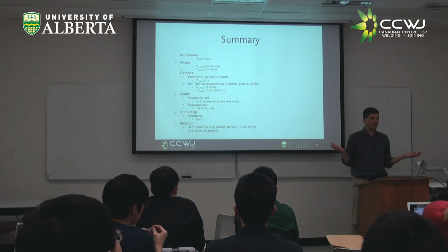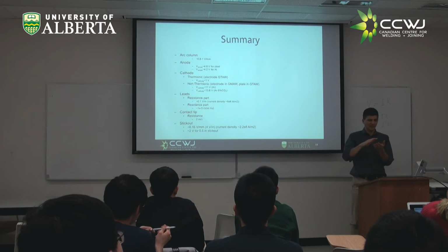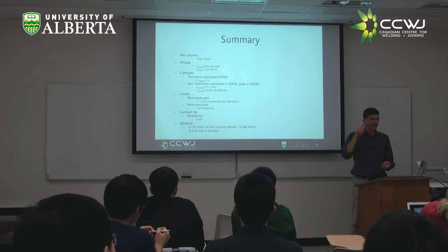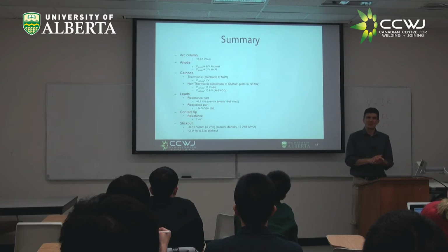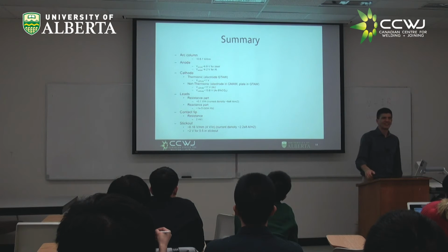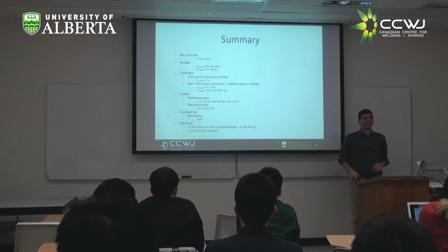The resistance of the electrode is more or less the same as the one I gave you here, right? But of course, it's a thicker wire and longer. And actually, it gets hot. I don't know how much role it plays. Dave mentions in the stick welding demo, and it was the first time I'd heard that, he talks about warming up the electrode. He claimed it was easier to start welding if the electrode was warm, which I hadn't heard before, but it seems to be the case.